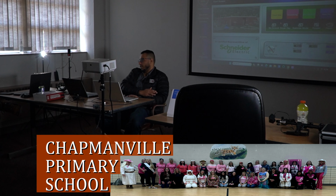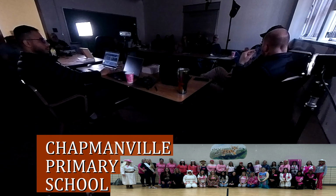No school is you overriding your occupancy schedule to be non-occupied for a certain amount of time. That's the no school calendar. The summer mode is to stop your outside damper from operating in any kind of position. Not economizer, not 0, not 100, not 10, not whatever. In other words, what he's saying, when it's summer mode, there can still be people working in the building, and it's still going to operate. But if you put it in summer mode and you hit no school, it's not going to work then.